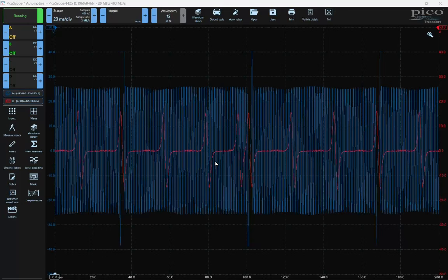I didn't acquire this data myself, but rather I downloaded it from Pico. Pico has a collection of waveforms which other technicians have taken from machines. Oftentimes, hopefully, it's a machine that does not have a problem. In this case, we can then use this as known good data if I happen to be working on a 9-liter myself and I have either a cam or a crank sensor fault and I'm trying to figure out what a normal pattern should look like and I don't have another machine.